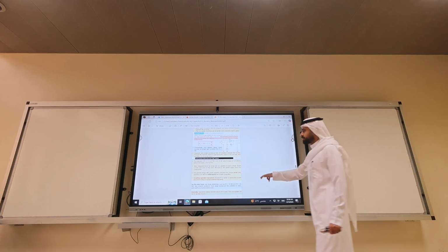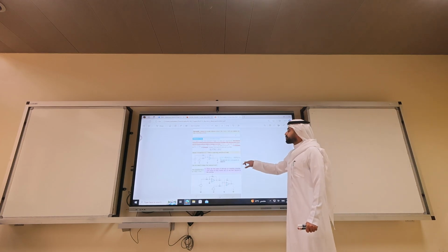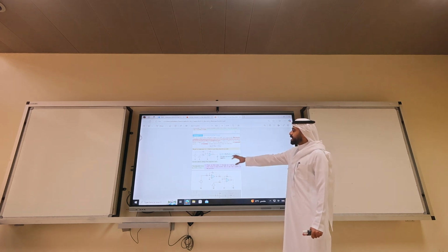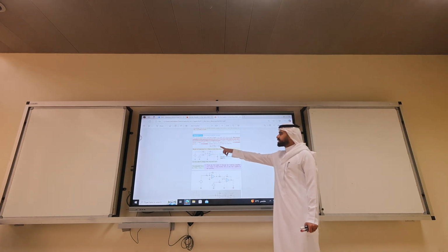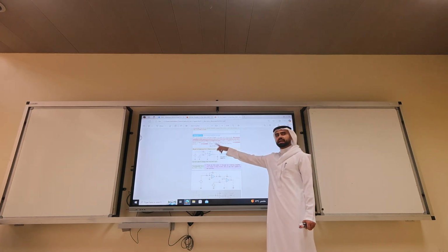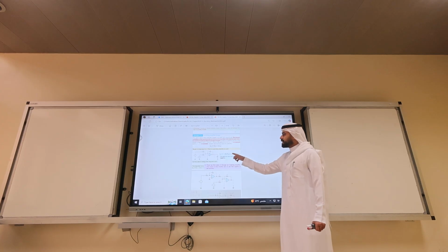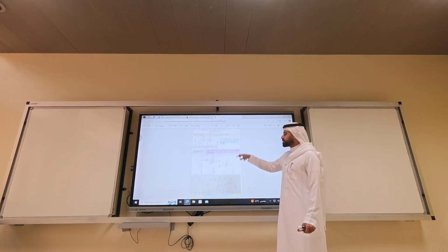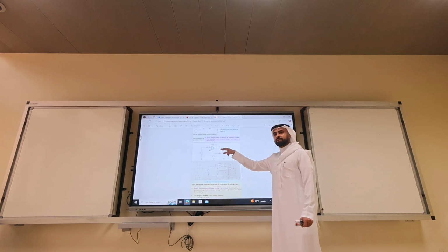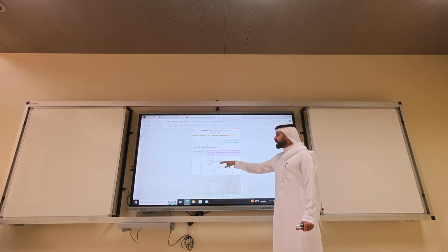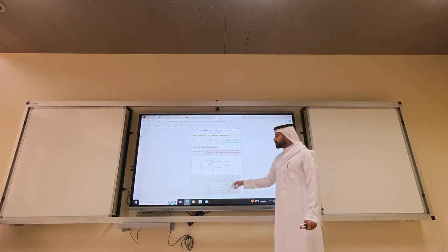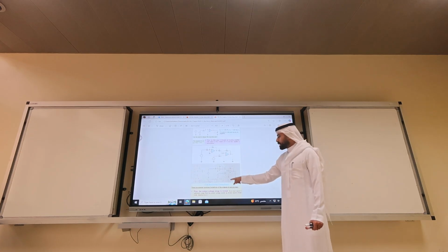Get it? Now, we usually find the combination for a summing amplifier design. The issue we had is that getting a positive 5 is not going to happen unless VA is already negative, because the ratio of two resistors is positive. So the solution is to use a non-inverting amplifier to invert the input, and then use a summing amplifier as stage 2. Okay? And you come up with a design.